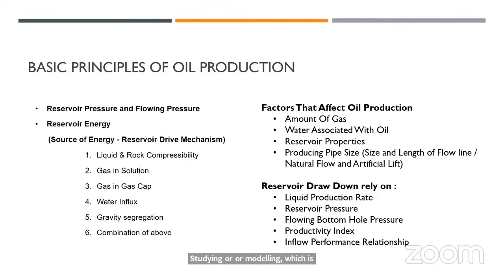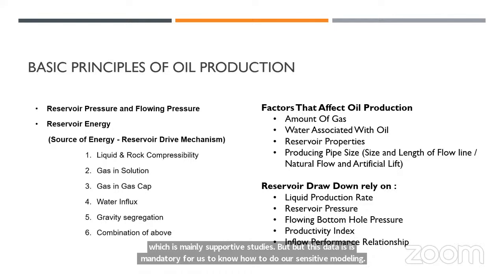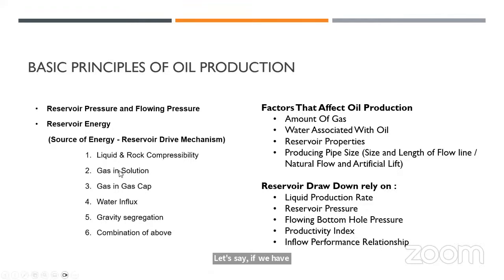But this data is mandatory for us to know how to do our sensitivity for the well modeling. Let's say if we have some gas in solution drive or gravity segregation, we might expect some depletion in this reservoir pressure over time. So we need to do some sensitivity analysis upon the reservoir pressure to know how the well will perform in the future if the pressure declines.